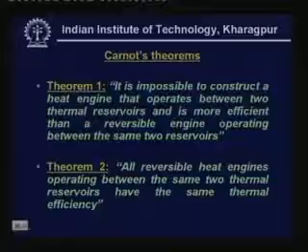That means the maximum efficiency is possible only with a reversible heat engine operating between the same two temperature levels. So this is the first theorem of Carnot. Now let us look at the second theorem of Carnot. The second theorem of Carnot says that all reversible heat engines operating between the same two thermal reservoirs have the same